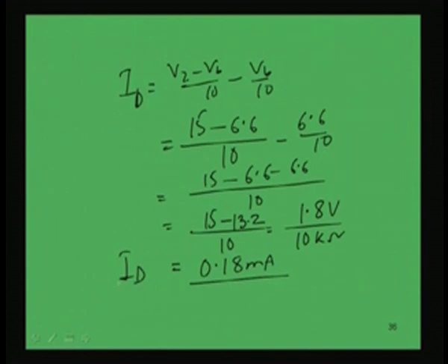So, in this example we have taken help of only the primary basic laws or principles, Kirchhoff's current law, Kirchhoff's voltage law only we have been using. So, in the diode circuits also, whenever you analyze the circuit, all those basic fundamental laws of electrical engineering like Kirchhoff's current law, voltage law, nodal analysis, all these will be applied, and the diode should be replaced by its model to fit into the circuit. It is not a physical diode now, we will be considering the approximate equivalent model of the circuit, that is the electrical circuit which will be representing the diode.